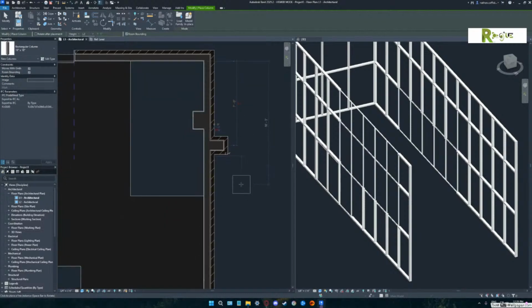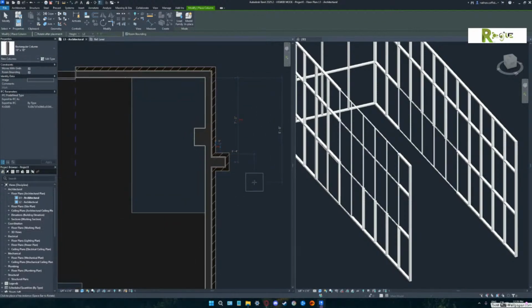Well, and we'll look at some floor plans, and what the gist of it is most people would think if you look at that, that looks like it's one wall, two wall, three wall, four wall, five walls. Instead, it's really just one column and one wall, or two columns and two walls. If you try to draw those little wrap conditions as walls, you will drive yourself nuts.